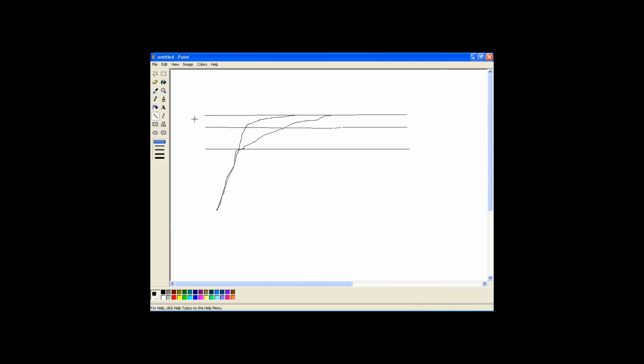On the same note, if you have a very small proportional band, let's say 2 degrees C, now what's going to happen is it's going to go 100% throttle right up to that proportional band, or 83 degrees C, and then it'll start to back off. And if it's too small, it's not going to have enough time to back off, and you're going to get some overshoot, and then it'll try to come back in and more control.